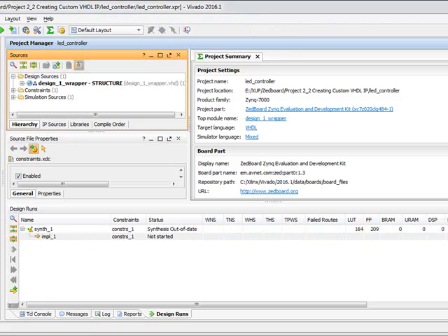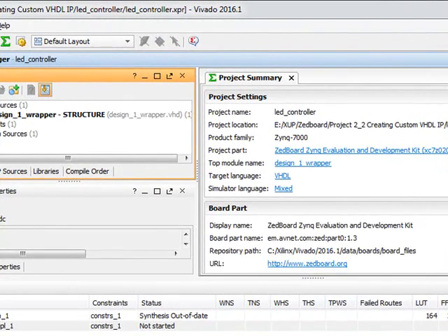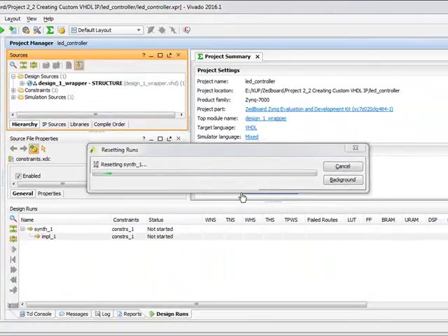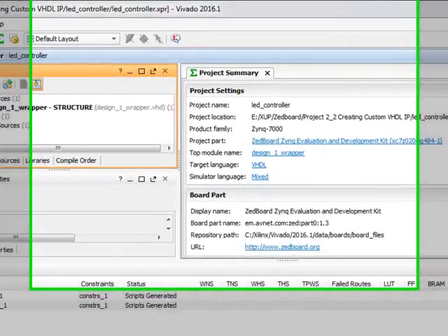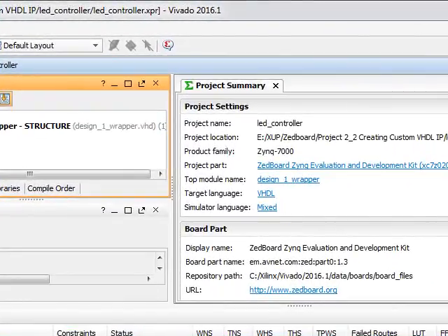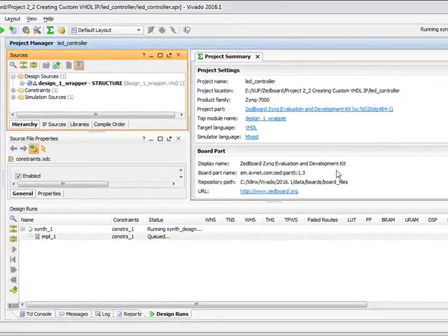So let's click on Generate Bitstream. It will do the previous processes also, so let it run. Okay, it synthesizes the design again. Actually we must have inserted our constraint previously, and then followed synthesis. We did it the opposite way, so here it is somewhat time-consuming. So let's wait for the bitstream generation.